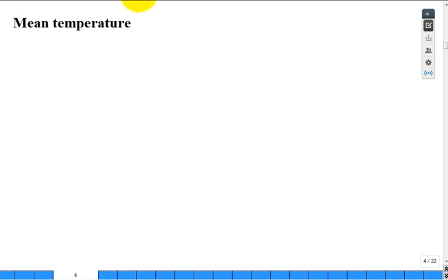Because we just had a profile like this and we said, oh, if the wall is hot, you get a profile of temperature in that flowing fluid such that if it's turbulent especially, it's going to be well mixed, and so the core will be a pretty uniform profile, temperature pretty constant, but then it's going to be higher if the wall is hot as you move toward the wall, right?